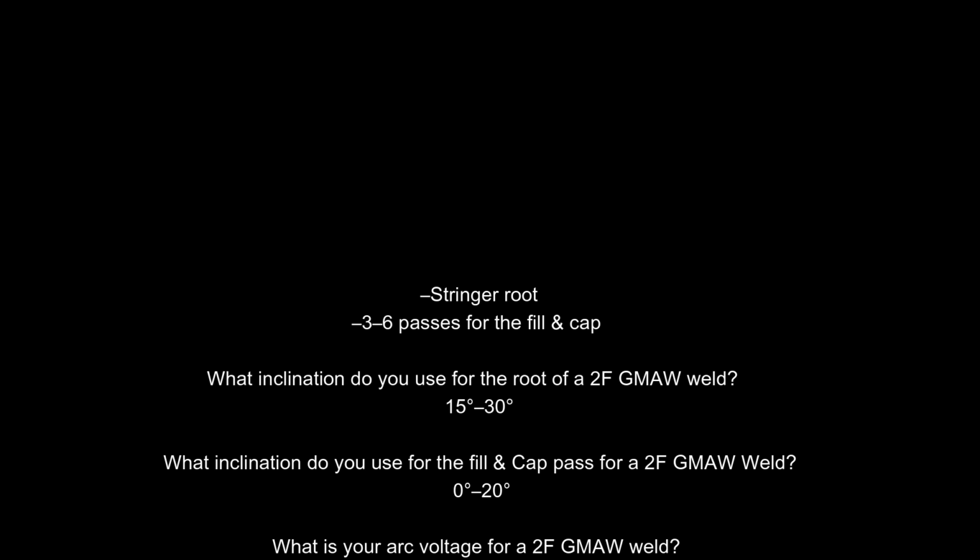What is your arc voltage for a 2F GMAW weld? 18. What is your amperage for a 2F GMAW weld? 120. What is your wire feed speed for a 2F GMAW weld? 180.